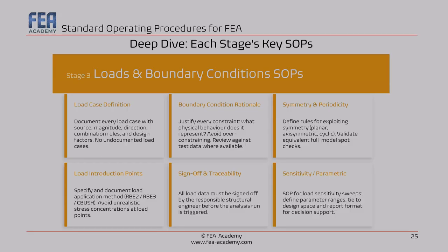You understand that? So the SOP answer: every constraint must be accompanied by a written statement of what physical behavior it is intended to represent, and a qualitative assessment of the sensitivity of the results to that assumption. And it is not optional. It is the engineering rationale for the model. And it's very simple to put in place.